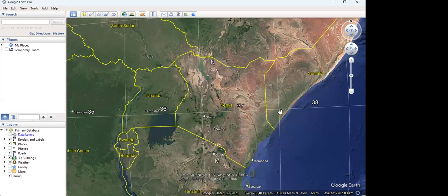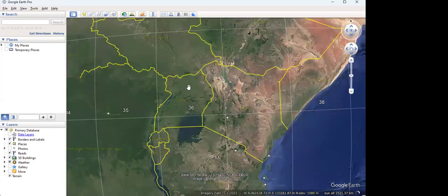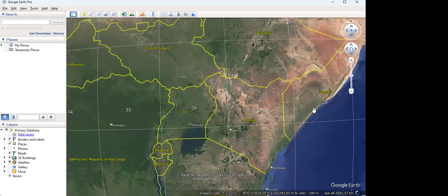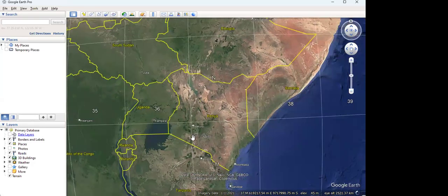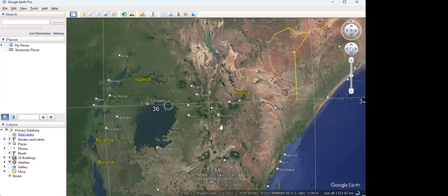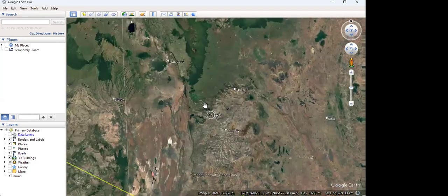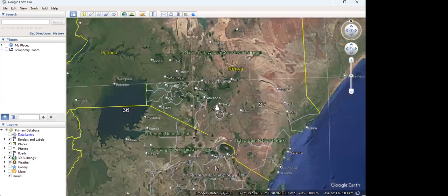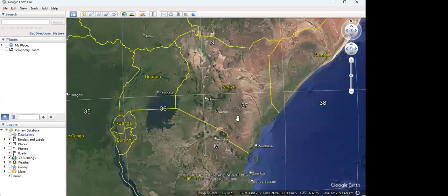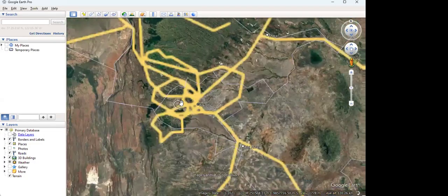But also, we are bisected by the equator, this one. So either you're in 36 north or 36 south, either you're in 37 north or 37 south. This is how our country is divided. Our area of interest is in Nairobi, and you can clearly see the zone where we are. This is 37, but on the southern side. So our zone will be 37 south.